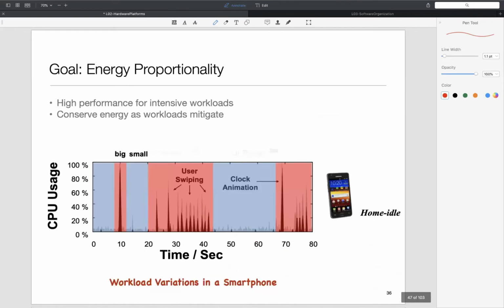Okay, so with energy proportionality, and if your OS and/or application or hardware are doing their job correctly, what will happen hopefully is that when there is burstiness, when there is more load, then the big cores kick in. When there is little going on, then the tiny cores kick in, and you would never notice. Sometimes all this power management goes awry and the system doesn't do very well.